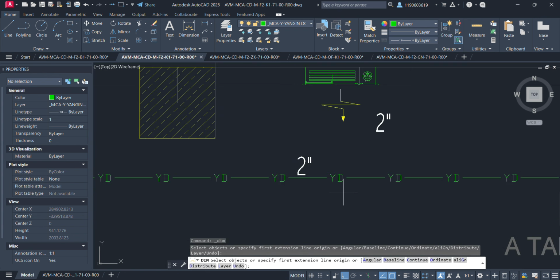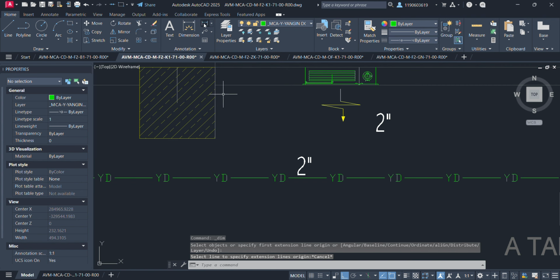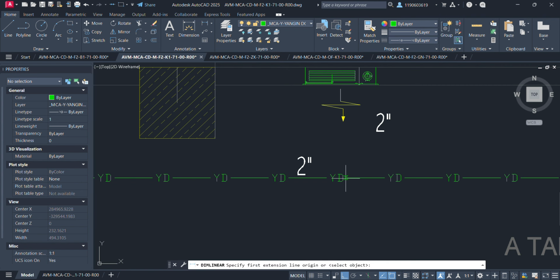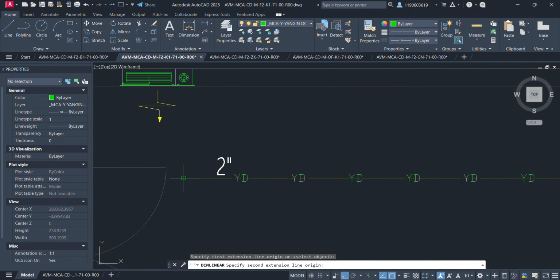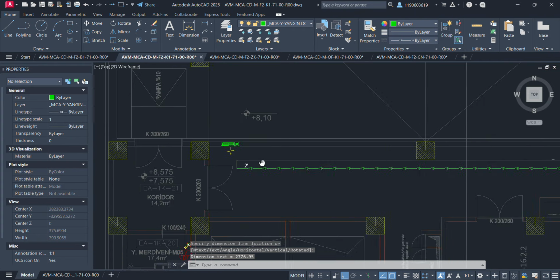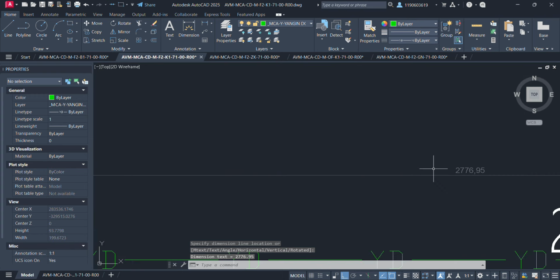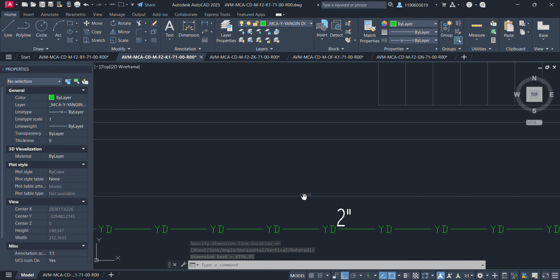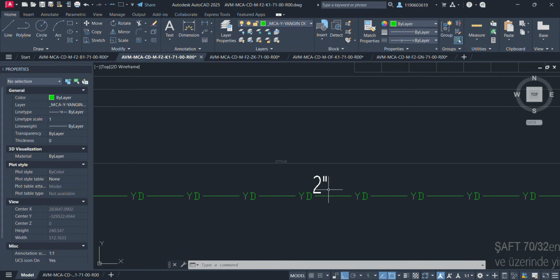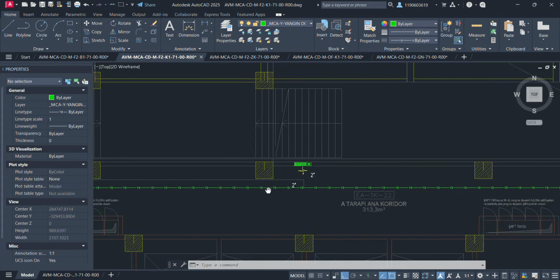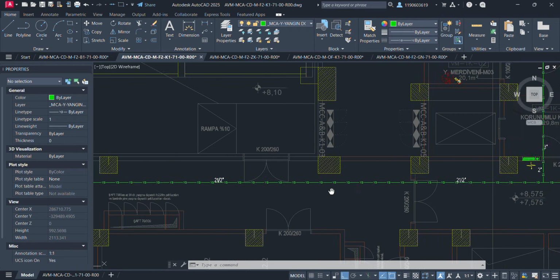Vertical or horizontal sprinklers. The type used is determined based on the room or space. Horizontal sprinklers are commonly used in corridors or large rooms, while vertical sprinklers are used in areas with low ceilings or limited spaces. Specialized sprinklers for hazardous materials. These types of sprinklers are designed for areas that contain flammable or hazardous materials. They are specifically designed to be more effective at extinguishing fires in high-risk environments.